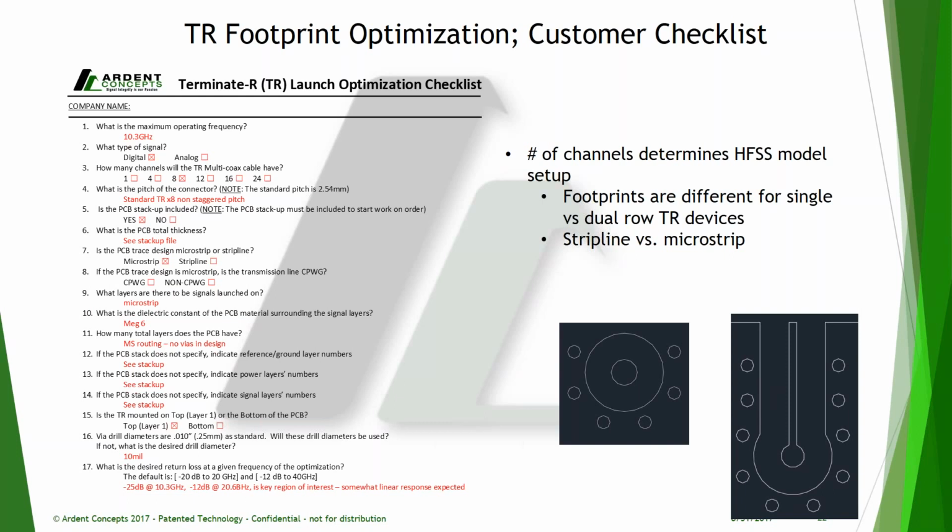Also, another question is number 7. And that question asks whether the trace design is microstrip or strip line. On the right, we have an exploded view, or a blown up view, of the standard TR footprint. And we can see that the strip line launch structure is slightly different from the microstrip launch structure. So again, we want to use this checklist to help figure out how to set up the experiment, the simulation, most accurately.